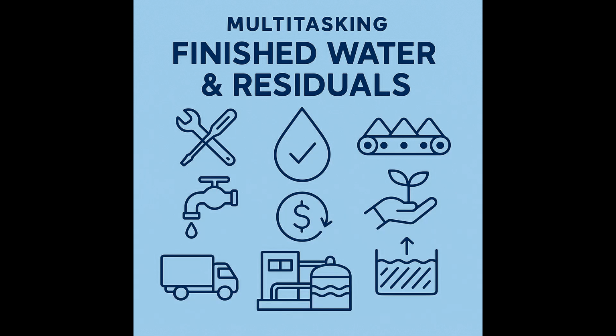Okay, let's shift gears slightly and talk about one specific disposal option that comes up, especially with certain types of residuals. Land application. What exactly does that involve? Land application in this context means taking the dewatered water treatment residuals, or WTRs, specifically those resulting from using aluminum or iron salts as coagulants, and spreading them on permitted agricultural fields or sometimes land reclamation sites. In Virginia, this process is typically regulated under Virginia Pollution Abatement, or VPA, permits.